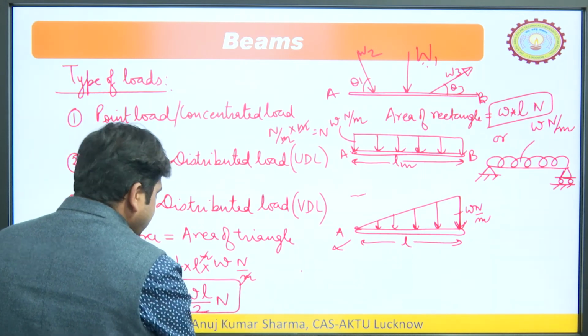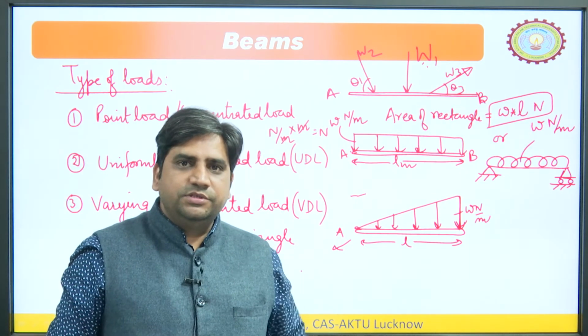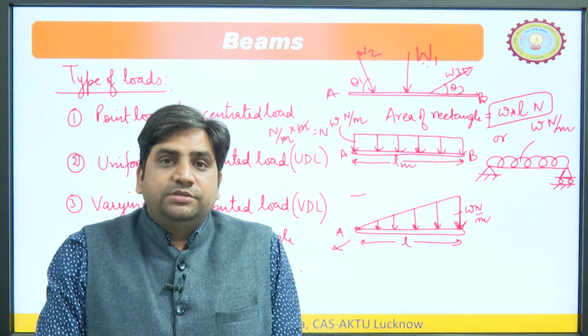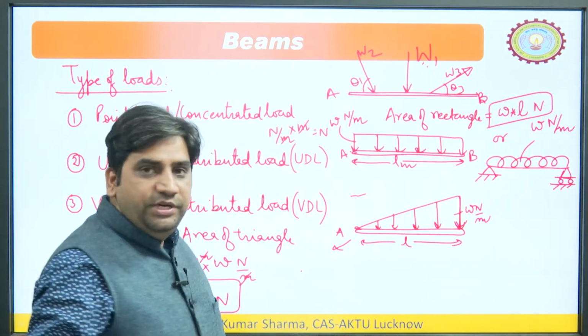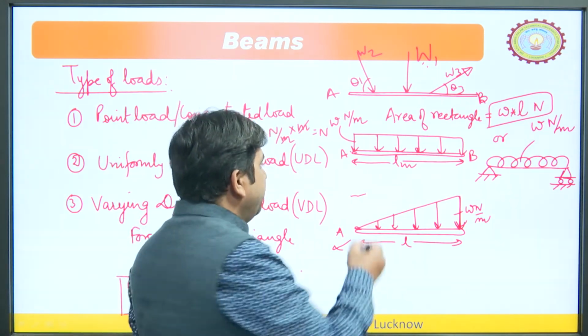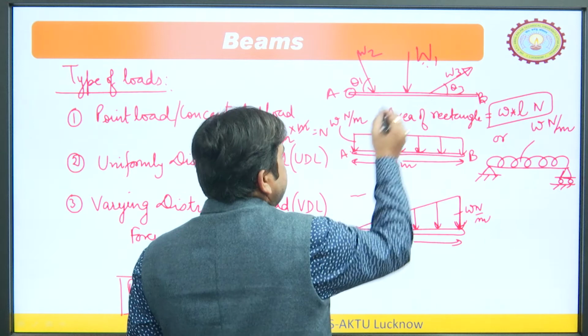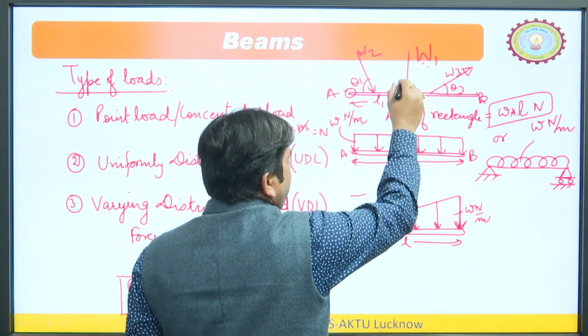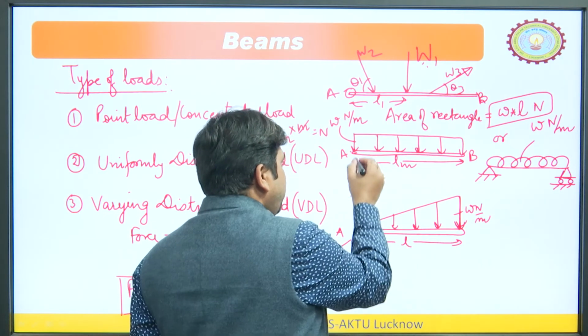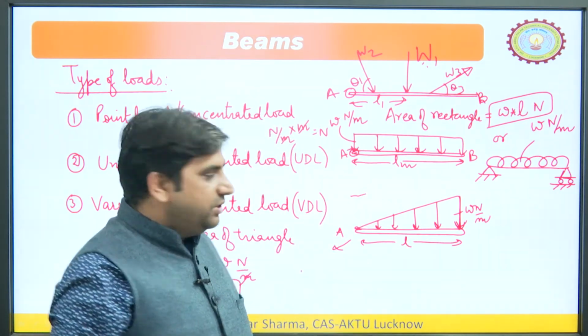So, now we can add vertical components of all these forces to get the total force, but the next question arises where we will apply these forces, because we need to calculate the moment also. So, let us say we want to calculate the moment about this point. So, easily we can calculate the moment of this W 1 is equal to W 1 into L 1 clockwise, but what would be in this case?